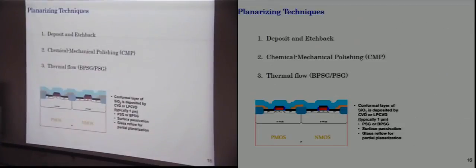So, how do you actually do planarization? These are the 3 techniques for doing planarization. We will talk about deposit and etch back, chemical mechanical polishing, which is the most predominant one, which we will spend more time on, and we have also this thermal flow, BPSG, PSG.